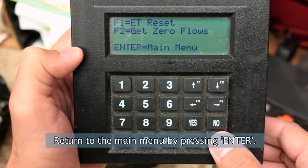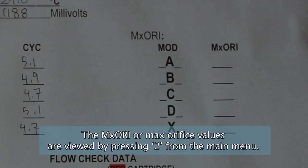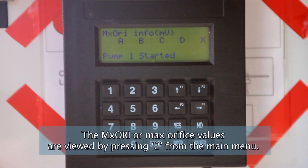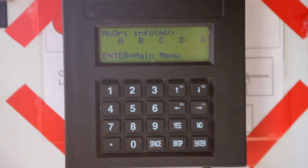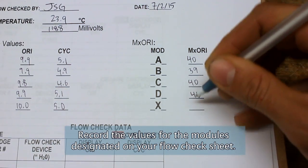Return to the main menu by pressing Enter. The MXORI or max orifice values are viewed by pressing 2 from the main menu. The pumps will turn on and display the values for all modules after a few moments. Record the values for the modules designated on your flow check sheet.